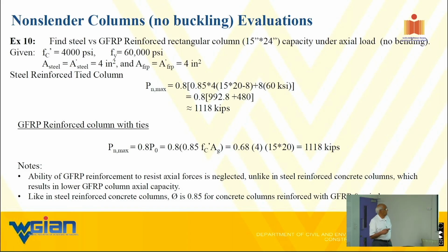And especially, if you remember, I used the word 10% thing, you recall? If the applied load is less than or equal to 10% of this equation, that means you don't have to worry about any bending related issues.